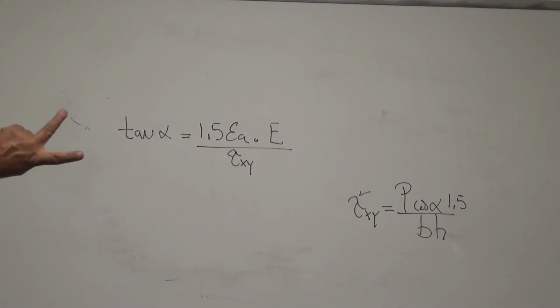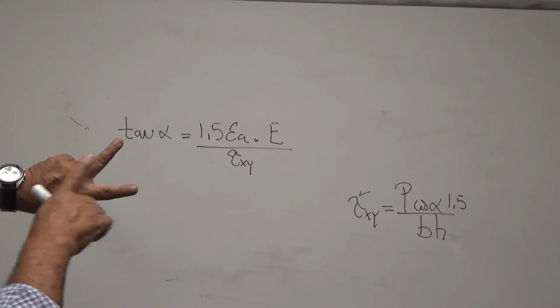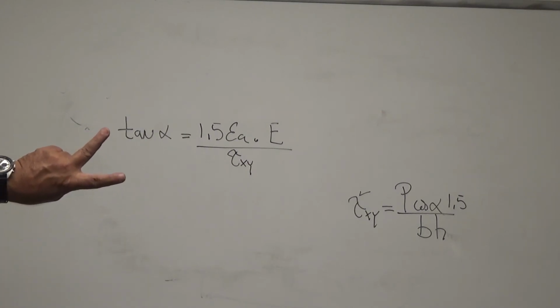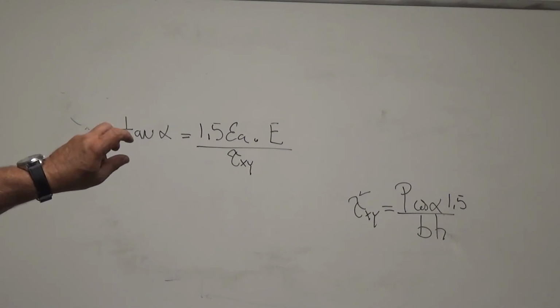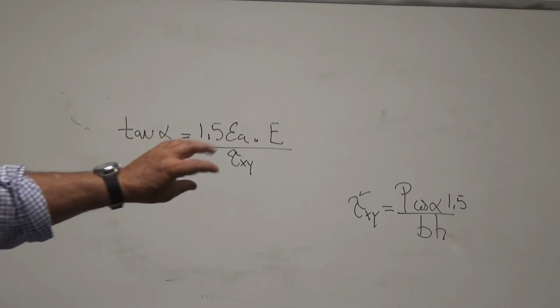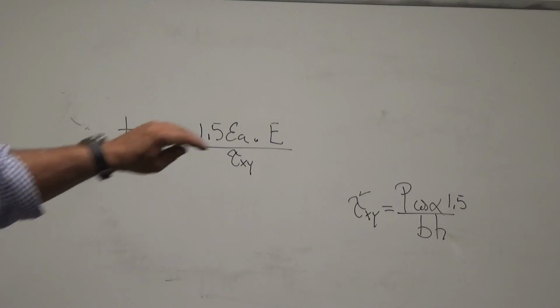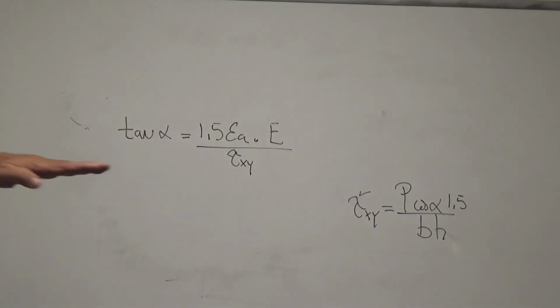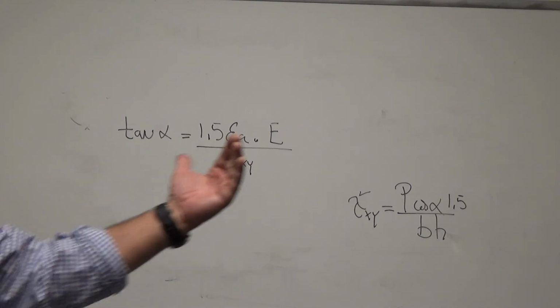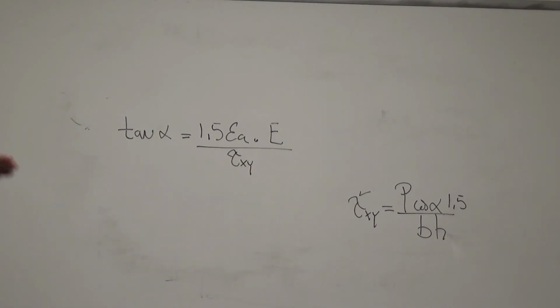We have two strain gauges, one that measures horizontally, one at an angle. We use the one at an angle to give us the shear strain. Once we have the shear strain, we can get the shear stress. Once we have the shear stress, we got an equation that connects it to the load in this direction. We also measured horizontally. That allows us to connect it to the horizontal component of the P. We get two equations, combine them, solve the problem. I substituted the numbers and checked, and the book is correct. The answer in the back coincides with what we get.